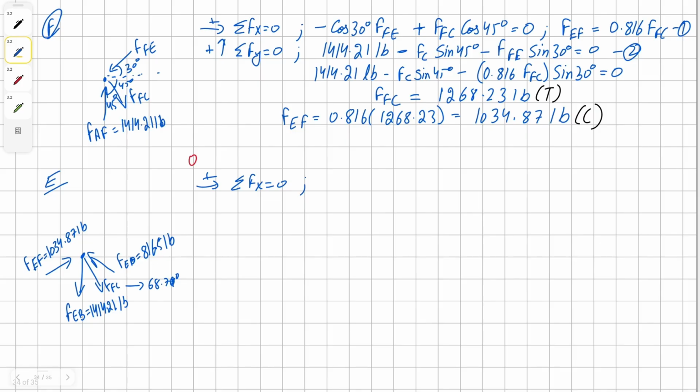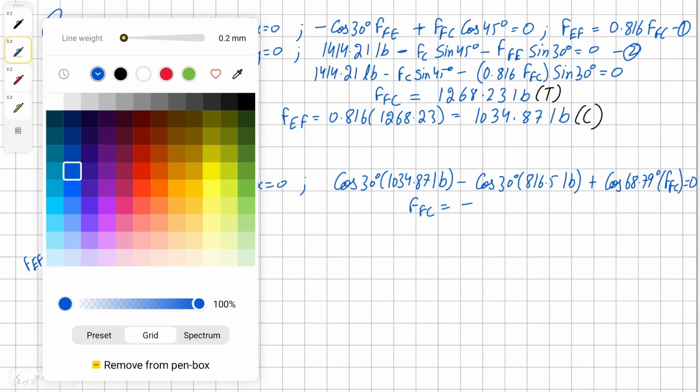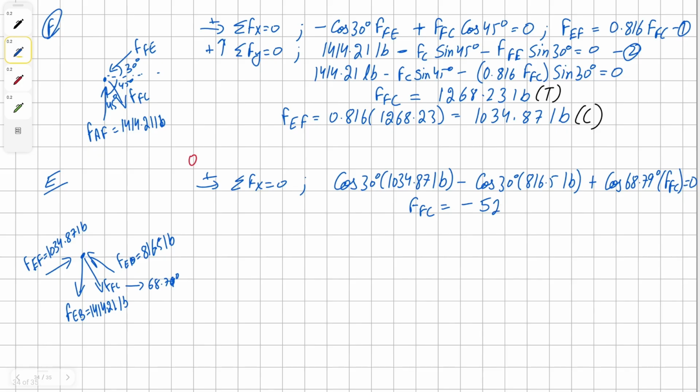Alright, now we can sum the forces in the x direction to find a solution for unknown member EC. It's going to be the horizontal component of EF and ED, and also the EC. We get our solution for EC as 522.72 pounds. Since it is negative, we need to switch our vector direction, giving us positive, and it also tells us that this member would be in compression.